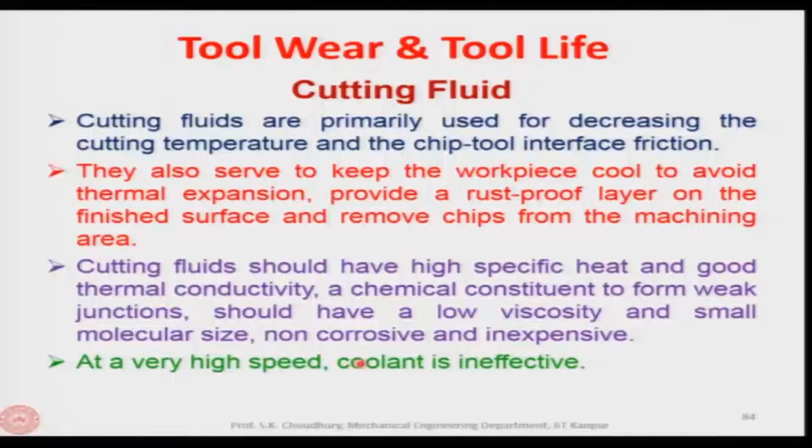At a very high speed, coolant is inefficient, because it cannot get enough time to reach the machining zone, and also it cannot get into the machining zone because of that wedge which is formed by the tool, the workpiece and the chip.